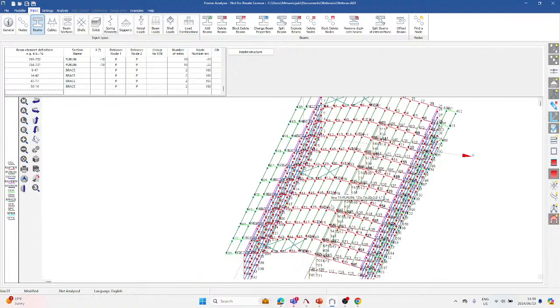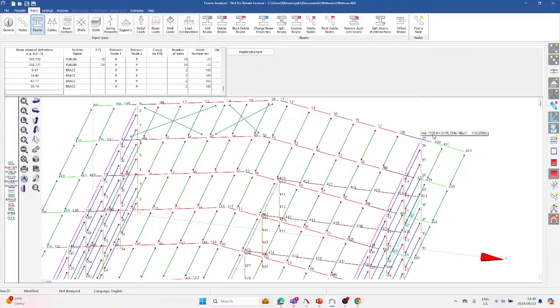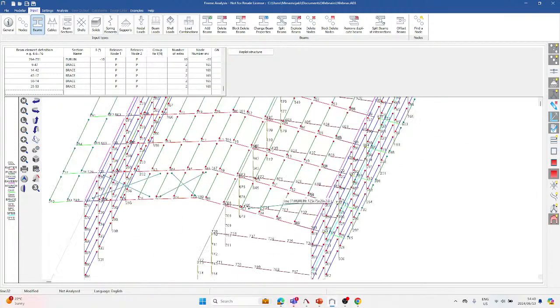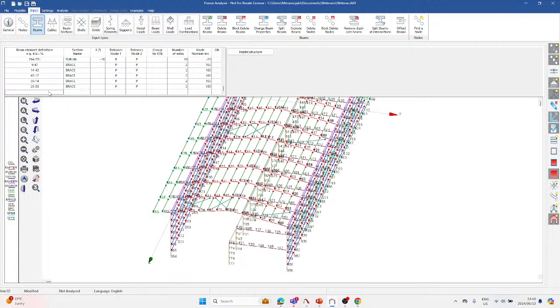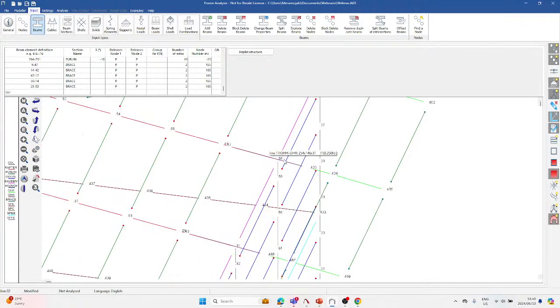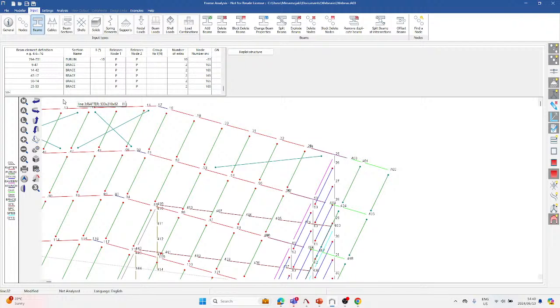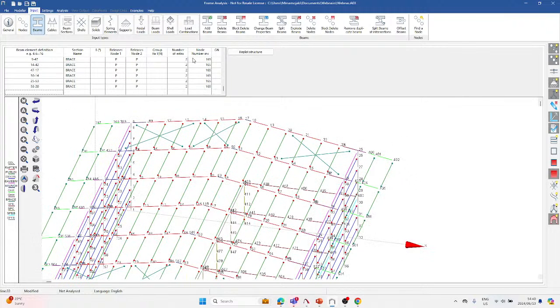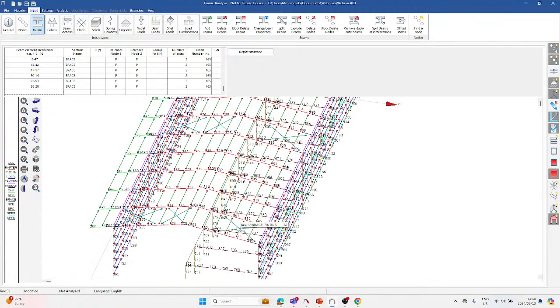And then I'm gonna add on this side the bracing from node 25 to 53, also brace, pinned, pinned, also 2 to 165, so that we copy it in the middle bay and also on the last bay. And then from node 58, which is that node there, to 20, still brace, pinned, pinned, 2, then 165. I want 2 extra, meaning it must copy it on the middle bay and also on the last bay.